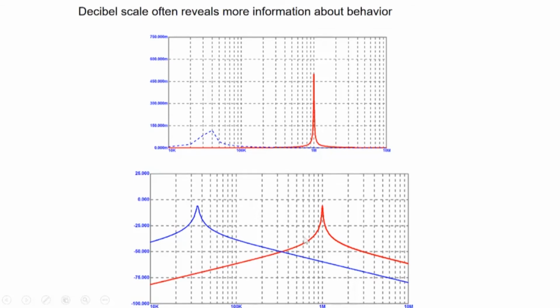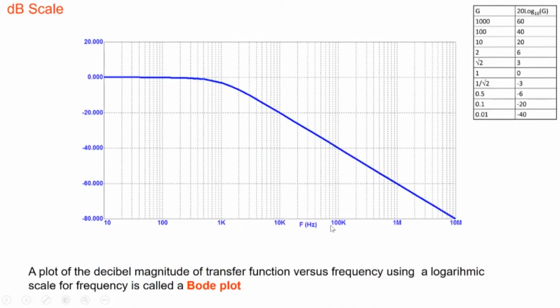So it is continuously reducing, and we can see the strength of a signal compared to the peak value more easily. For example, at this particular point, the signal is maybe 70 dBs below this one, and somewhere else you may say the signal is 50 dBs below here. And once you understand what the dB scale really means, then you can easily correlate.